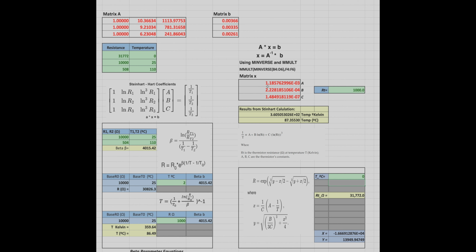We're on the low end here at 6.7 on our reference. The first reading is from the epoxy thermistor, and the second reading is from the Honda engine coolant temperature sensor. It looks like the epoxy is fairly close to our reference.